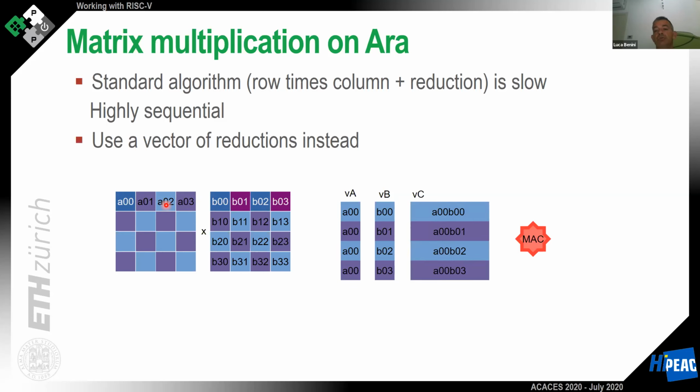So we are going to fundamentally use the floating point multiply accumulate units in the lanes to accumulate the partial products of the row by column that we are computing in parallel with our vector lanes. So you take the first operand and you multiply it for the first 4 columns in parallel, using the 4 parallel multiply accumulate.